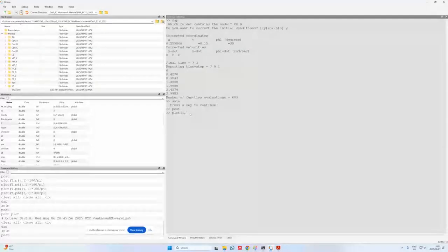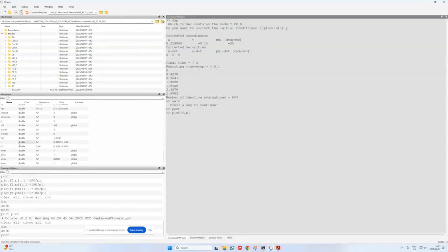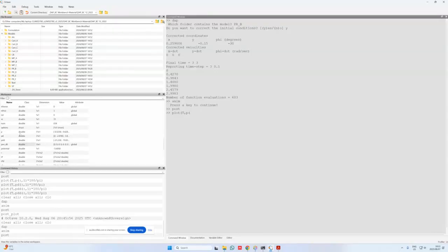Then what I want to plot on the y-axis will be the angle of the pendulum rod. So I'm going to type in P, and if I have a look again at what the form of P looks like, it's a 31 by 1 matrix. So the number of time steps by the number of bodies. I'm only working with a single body, so I can technically type in over here P. I want to plot it for all times.